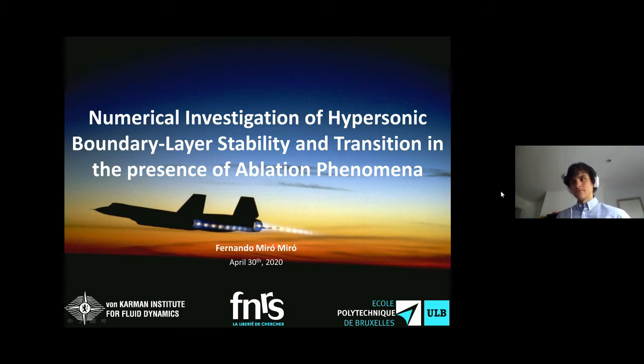I have a sort of question going back to where we started, years ago. Sometimes we have to go through very harsh simplification in our modeling, and for instance, one of these things is the shock boundary condition that I already implemented, and then we verified that, in the injection and the shocklet caused by the injection of lighter or heavier gas, considering or not the shock boundary condition has a strong impact on the evaluated stability of the flow.